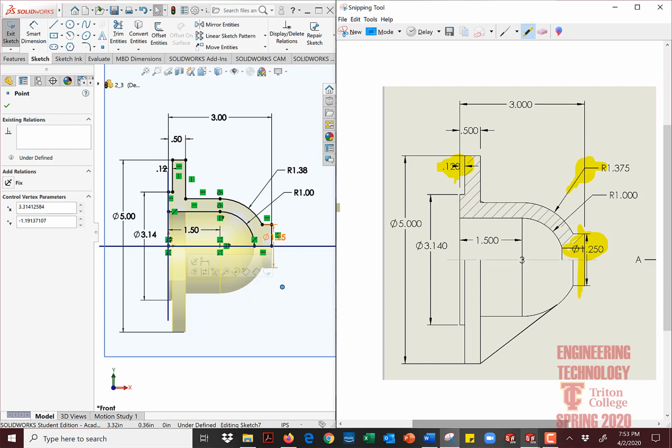That is the reason you hear me say, however you want the dimensions to appear in your detail drawing, that is exactly how you want to place them in your model. That is also the reason that I tell you over and over again, never delete your smart dimensions from your model. If you delete them from the model, they delete from your detail drawing. And outside of the obvious thing, they also unconstrain your object. They also make it impossible for you to have your dimensions popping into your detail drawing.